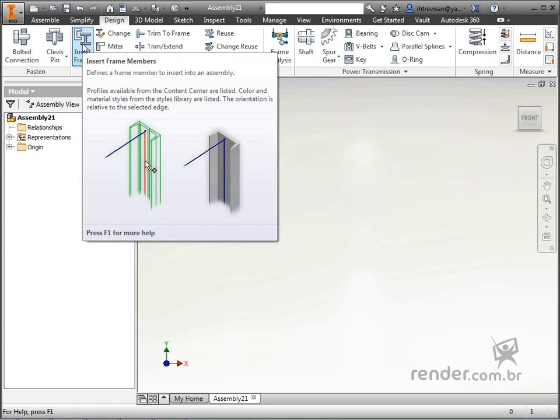The process of creating the structure consists of drawing a set of lines, representing the entire structure, and applying the InsertFrame to add the elements to those lines, projecting each profile as needed. This process provides a time gain over the process of inserting components from the Inventor standardized element library. Therefore, these design tools are called design accelerators, as they accelerate the design process.